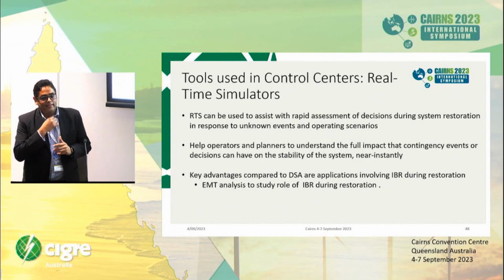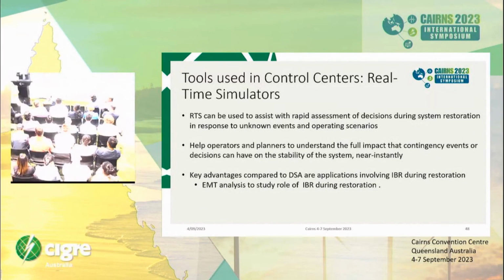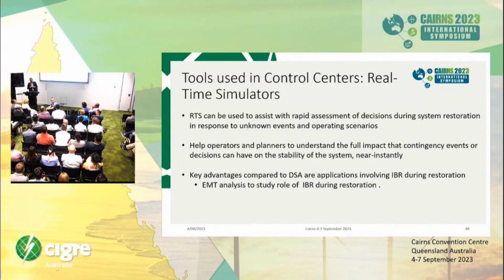My question is on the previous two presentations. You mentioned in the first presentation, about energizing transformers and lines, two methods. One is oversizing the inverter, which is expensive, and then you talked about soft energization. Have you considered in your study the fact that sometimes you can soft energize the first transformer, but you have another long transmission line and another large transformer before you even reach the stabilization load, which means you are forced to hard energize the line and the second transformer? Obviously, you'll be left with the expensive option, or what have you thought about other options in that scenario?